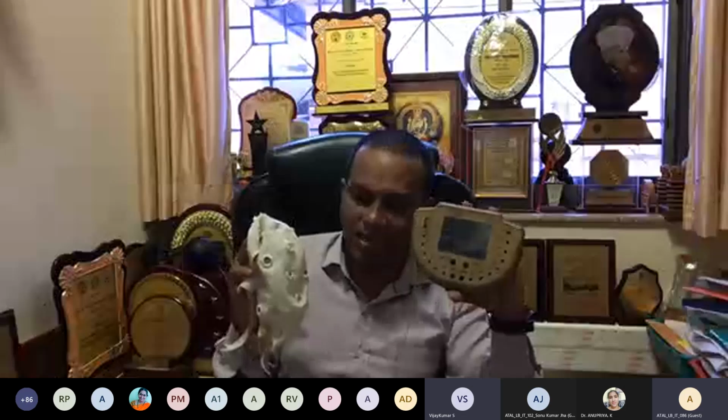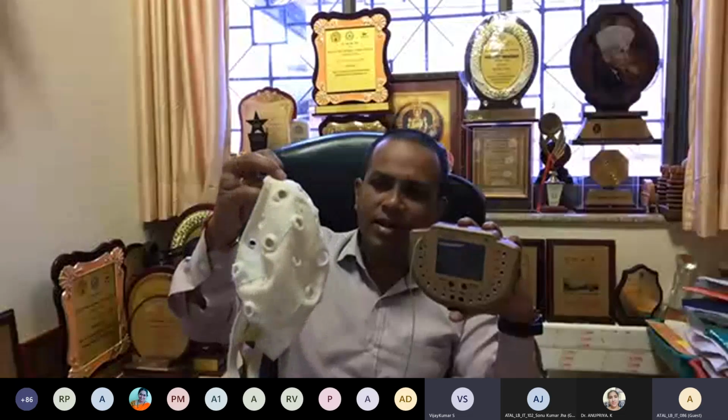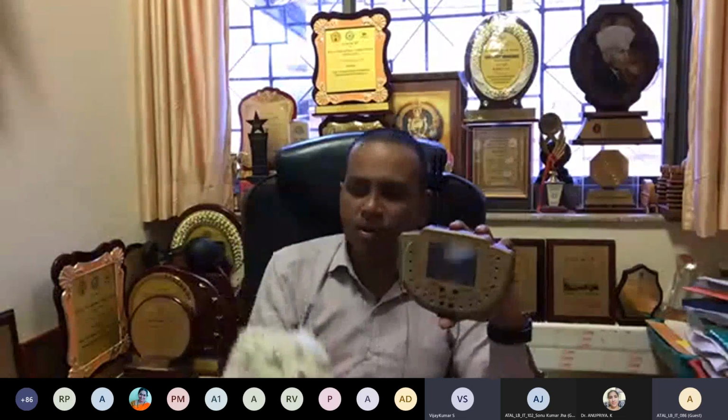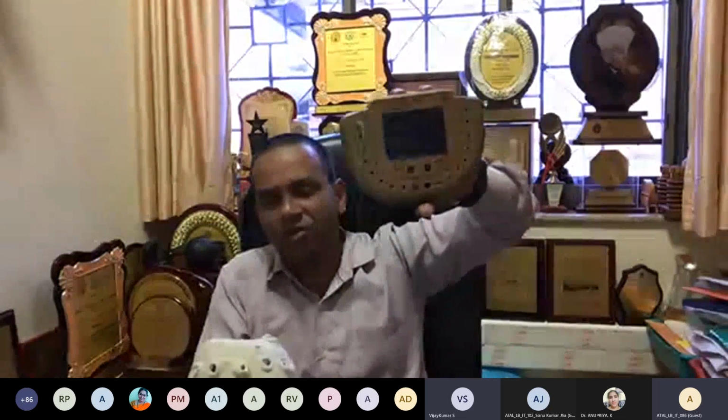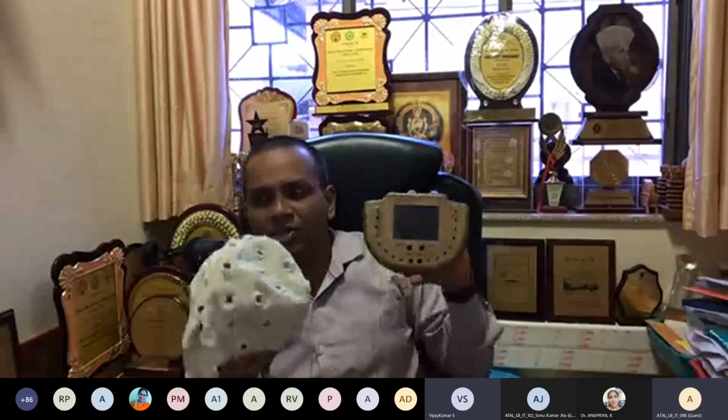Now we're not talking about the capacity of a data acquisition system. Now I'm talking about the size of the EEG cap. When you say 32, it means a maximum of 32 channels, so at a time, 32 brain locations you can take data from using this cap. So 32 channels are available here to place the electrode, but this machine's capacity is how much? Only 16.